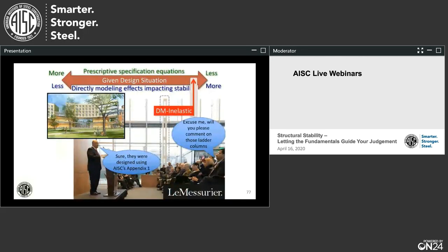This was an example in Boston that my friend Rich Hennig from LeMessurier lent me. They needed to provide a big column-free atrium in this building here. It's a business school building, and they wanted this big column-free atrium. And the architect wanted no columns, but LeMessurier's company didn't want to go with a big bridge over the top. So what they decided to do was still use columns, and these are big, hefty columns, but they cut the webs out of the columns, and they created ladder columns. All right, so big, giant columns here, but they turn them sideways, and they practically go invisible.